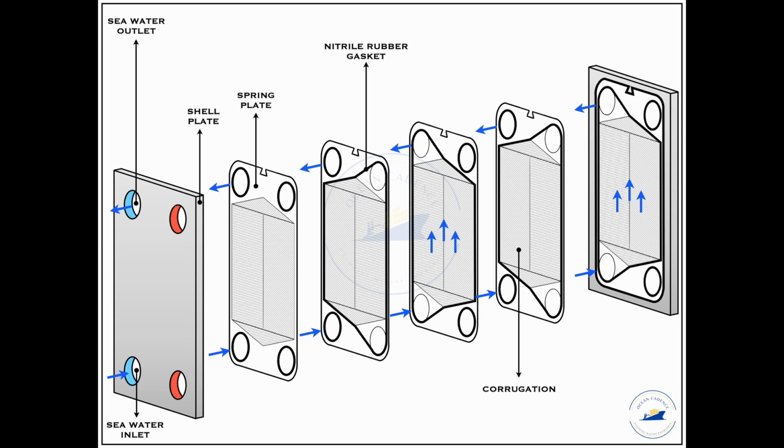Why it is so is because it allows for the channel distribution of the liquid, that is, it separates the flow of the liquid into small channels, provides turbulence, and also provides unidirectional flow as it moves upward, or vice versa downward in case of a downward facing corrugation, and by doing so it allows higher heat exchange efficiency to occur in the cooler. So the fluid will pass upward and then finally join the stream of the fluid that